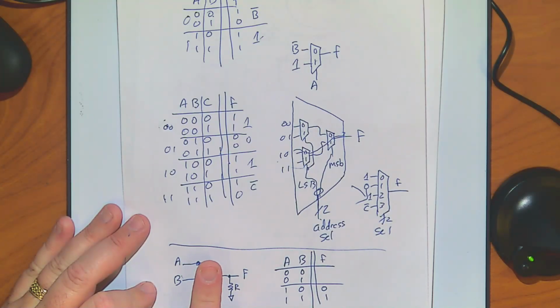So what happens to the circuit? It's not Z anymore because I've got that pull down resistor. There's not going to be a lot of current flowing through this, right? Once it's pulled through, that's just a path to drain any charge. So if it was high, it'll pull it down. And once it's pulled down, there's no more current flowing, so power stops flowing. End of story. So that's kind of a draining path.